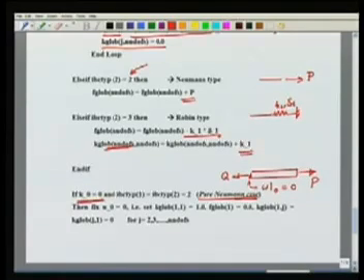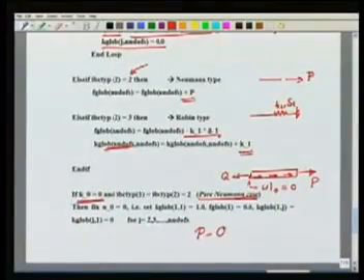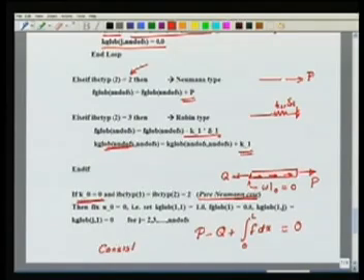This is because my loads have to be in static equilibrium. Remember, one condition that has to be checked for the solution to exist, that given this load p, q and the distributed f, p plus integral of f over the length minus q has to be equal to 0. That is, there is global equilibrium for the whole structure. If that is not true, you cannot have static equilibrium for this particular case. This thing, that p minus q plus integral of f dx from 0 to L is equal to 0, is called the consistency condition. This your load has to satisfy.